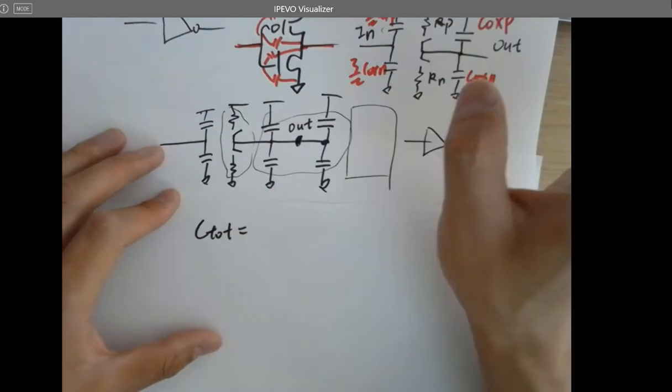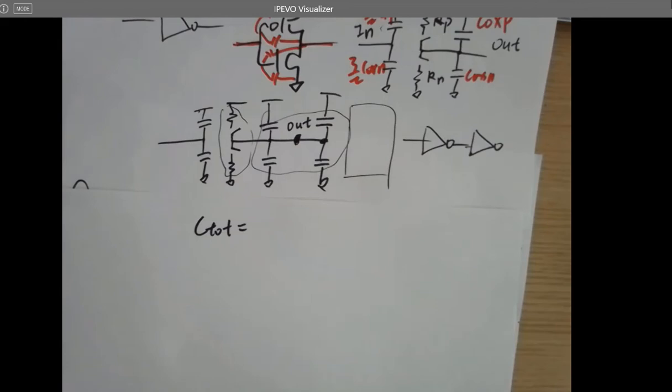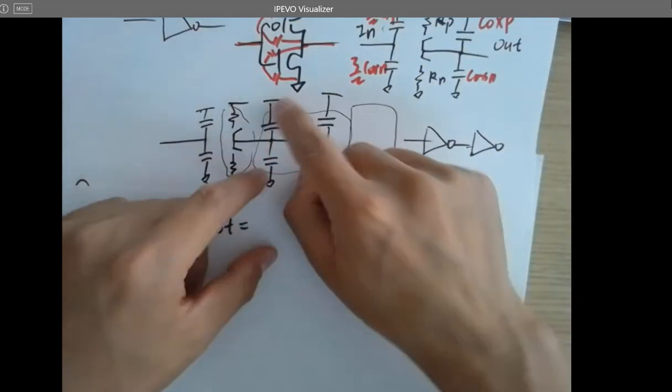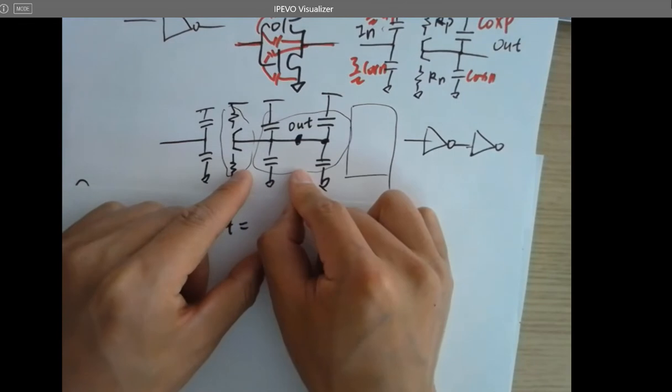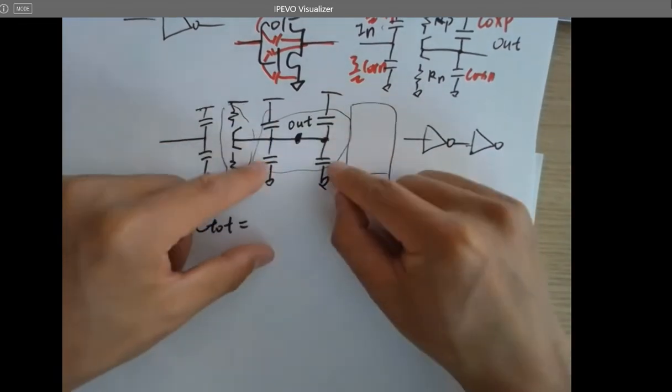It's confusing people all the time. It's going to confuse everyone for many years. But for now, let's just remember it: DC voltages are AC grounds. So when you are looking at these two, you want to flip it and short it to the ground. So actually you have 4 caps in parallel.